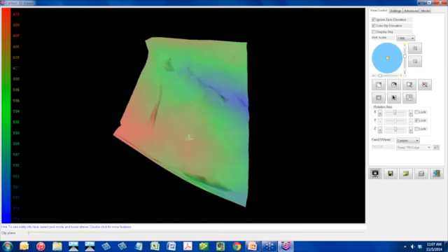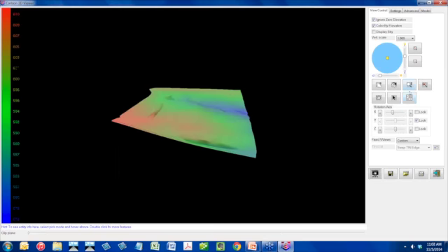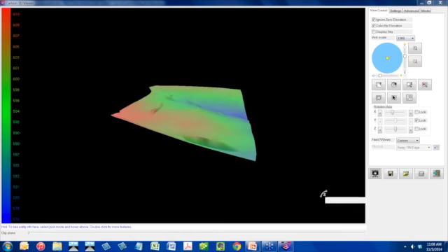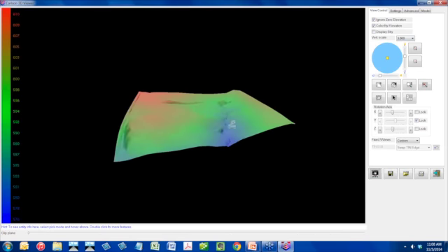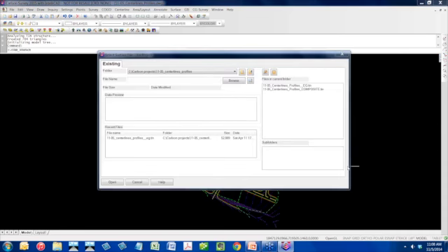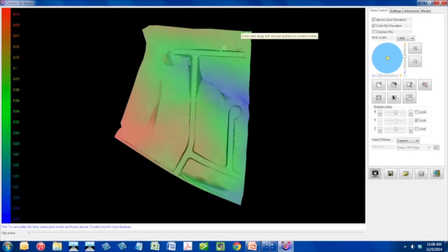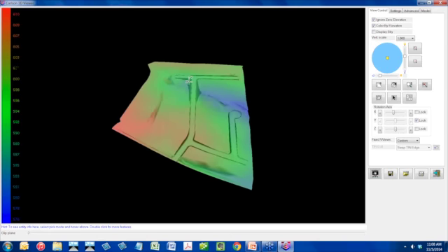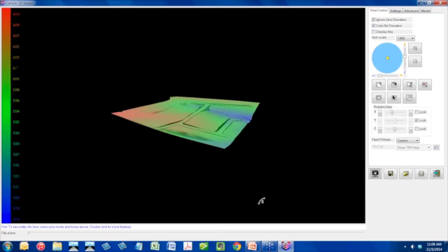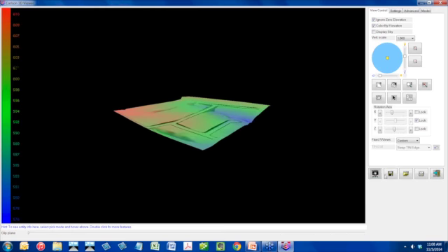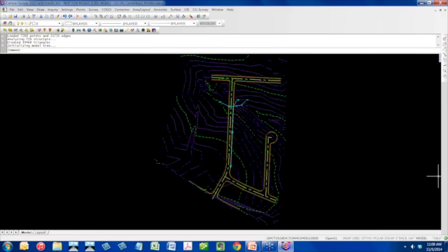So here in our 3D viewer, I'm going to tip it up. I can exaggerate the scale just a little bit, and move my GoToWebinar thing out of the way, and then spin it around so you can kind of see what our topography looks like in here. And then I'll just go right back into that and show you the composite tin. I'm not actually sure if I'll even use this, but this is where a road design has actually been completed and merged in with that existing surface. Okay, so I think those are the only files that I've pre-made in preparing and getting ready for this.